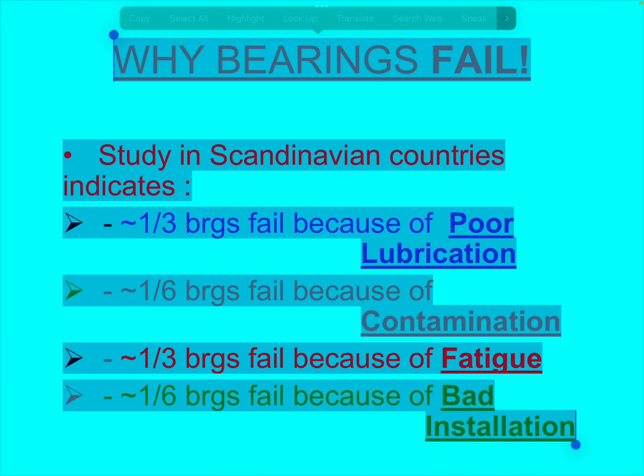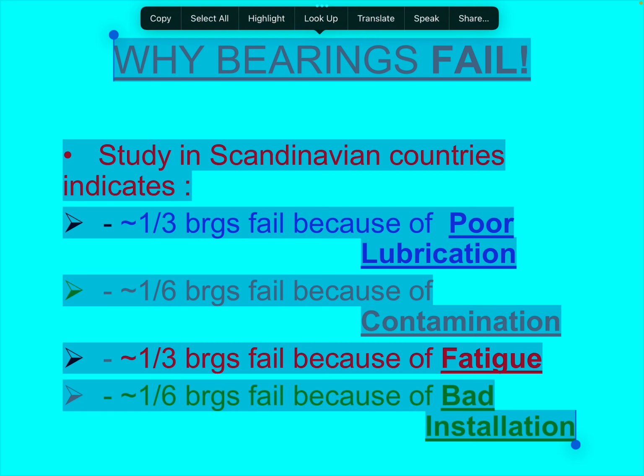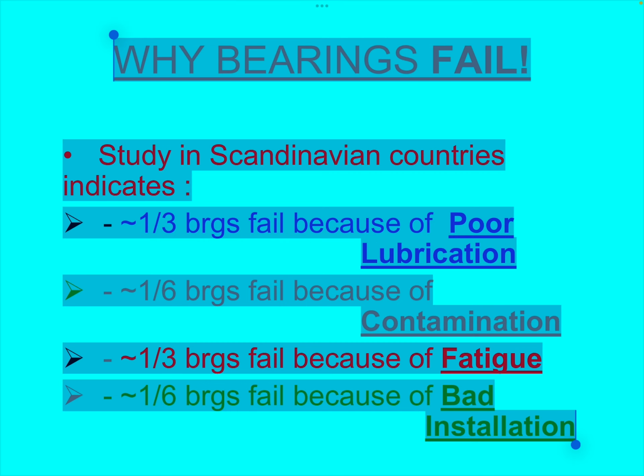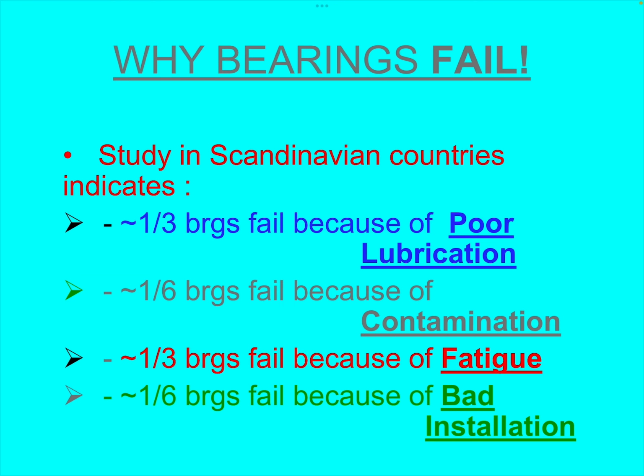Why bearings fail. A study in Scandinavian countries indicates 1/3 of bearings fail because of poor lubrication, 1/6 of bearings fail because of contamination, 1/3 of bearings fail because of fatigue, and 1/6 of bearings fail because of bad installation.